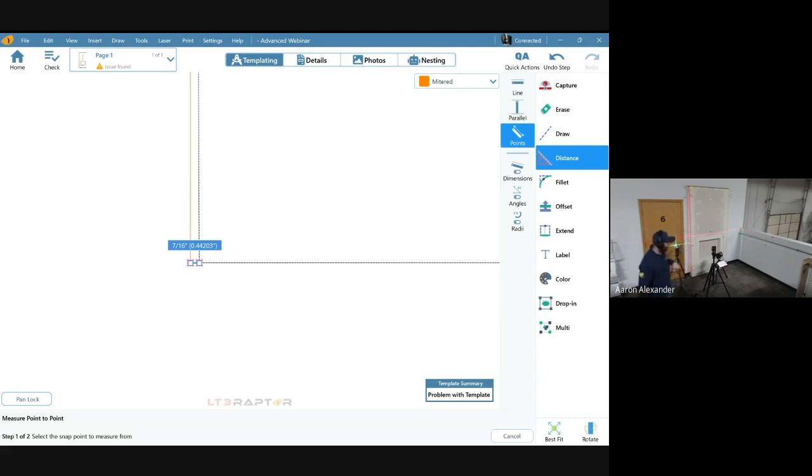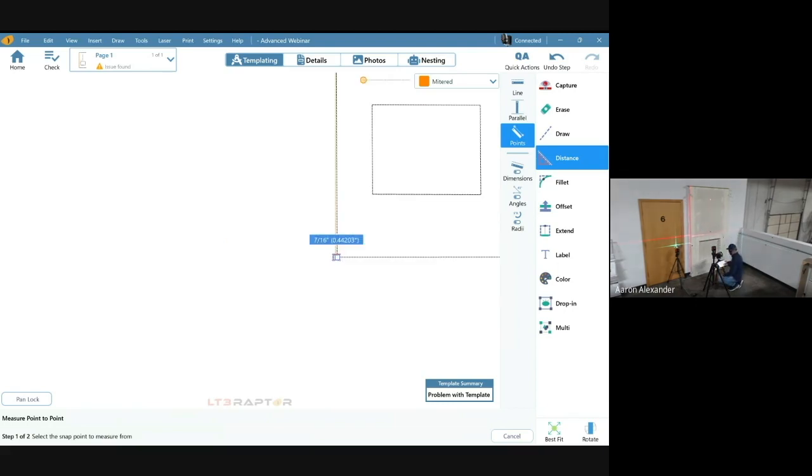Okay, so this is what we're going to do to plumb up all these edges here. Now, we're typically going to do, if we're doing 1.25" 3-strand material here, we're going to add that 1.25" for the offset for our miter. And then typically we're going to add some glue to that as well. So what we're going to do here now is we're going to go offset.